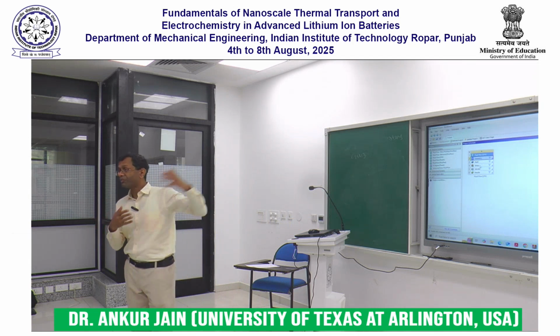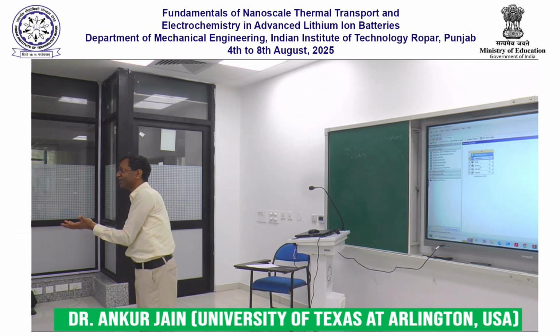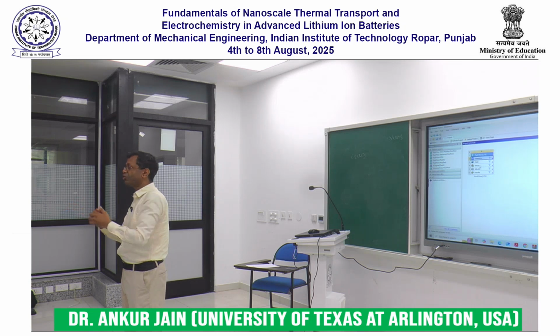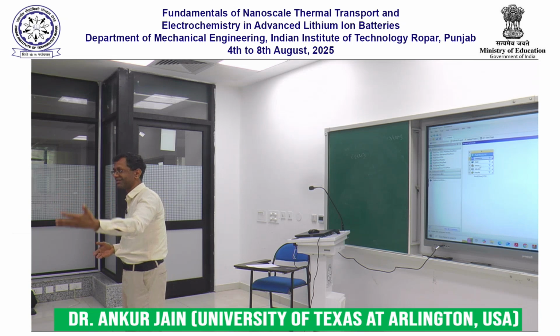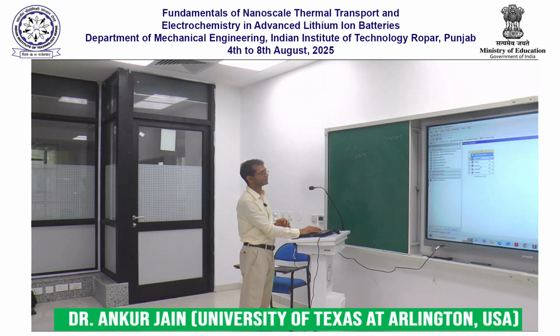You cannot possibly solve the problem, or Ansys cannot solve the problem, if it does not know what material the body is made up of, right? It cannot solve the problem if you do not tell it what the boundary conditions are. So you have to properly define the problem and communicate that to Ansys in a certain way that it understands. All of that we will do under setup.